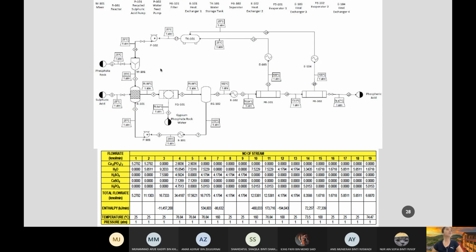But my advice, normally I will ask my student limit lah equipment dalam 10 to 15 equipment termasuk utility. Dalam ni ada berapa? 1, 2, 3, 4, 5, 6, 7, 8, 9, 10, 11, 12, about 10 to 15, normally. Kalau dalam 10 to 15 equipment, stream number kamu akan ada dalam 20 kepada 30 stream number. Kamu kena faham, 20 ke 30 stream number means setiap stream tu ada mass balance dia tau. So you imagine, if let's say you have stream number 40 ke 50, how are you going to do the mass balance? It become too complex. I did not advise you to do so, but if you want, okay je, I will help you to do it. Okay, so normally that's my guideline. Equipment 10 to 15, the most equipment sometimes goes to 20. Streamline not more than 30. 20 to 30 streamline is already good enough for me.